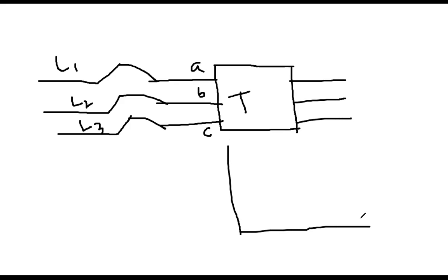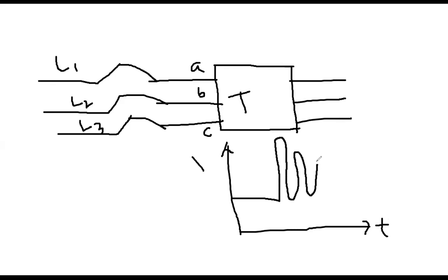That is the phenomenon. For example, I am plotting the current, magnetizing current for this transformer. So for example, it should be the normal value, but then because of this transient phenomena, current goes very high, very high. And then after that, what happens? It gradually decays. And then, you see, this is called the transient phenomena.